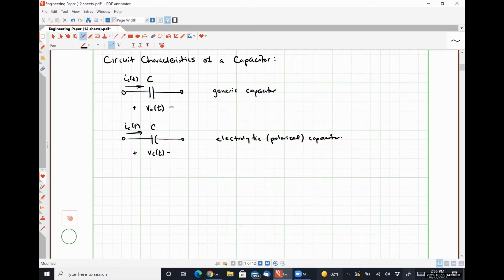If you plug in an electrolytic capacitor wrong, meaning that you apply a higher potential to its negative polarity side than you do on its positive polarity terminal, it bursts, physically breaks. So if you ever crack open a computer or something like that, and you look at the big capacitors in there, they're usually cylindrical looking circuit components with a little metal plate on the top.